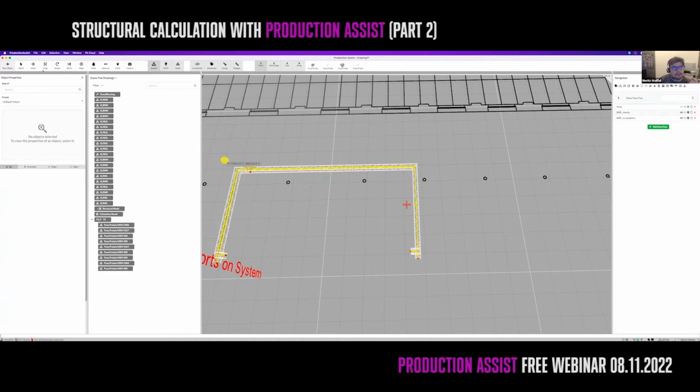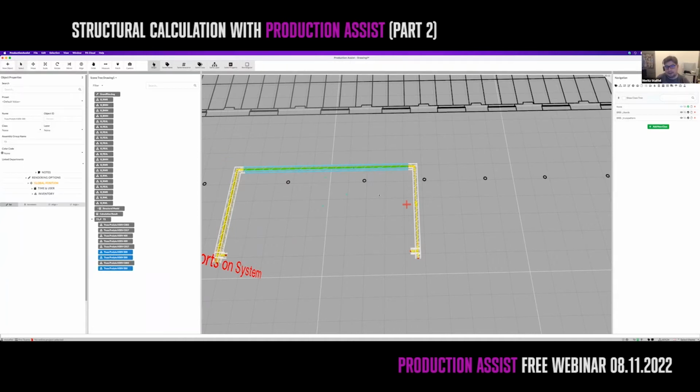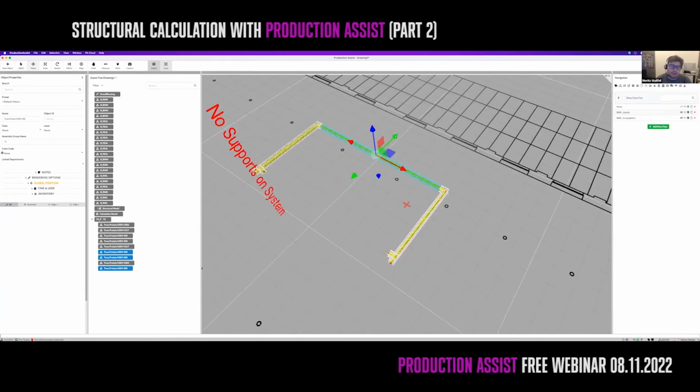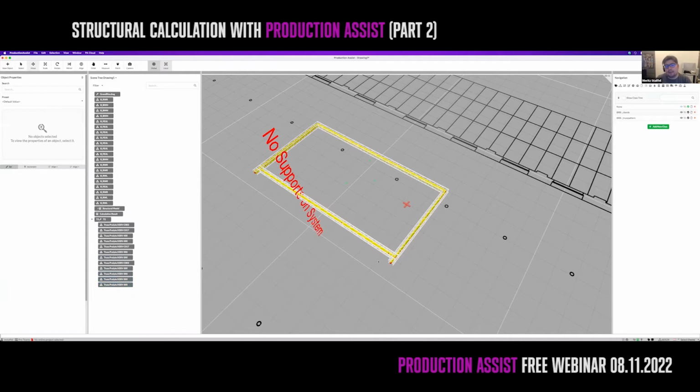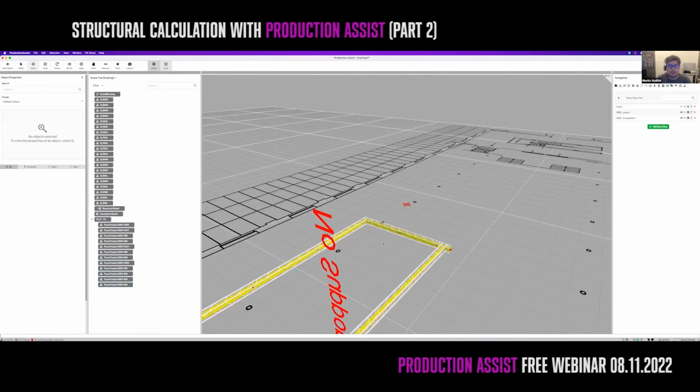Now we are a little bit lazy. I want to copy these 3 truss pieces so they are matching perfectly. In order to achieve this, I'm activating the Move tool and moving these 3 trusses while having the Option key pressed to here. I release it so that it's aligned, and then I have my new system.